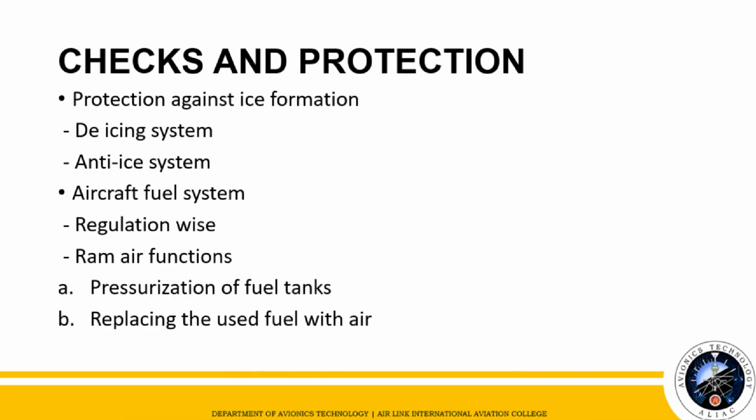Okay, so for the checks and protection, we have the protection against ice formation, which talks about the aircraft and engine ice protection systems, which has two designs, the de-icing system and the anti-ice system, which either remove the ice after it has formed or prevent it from forming.